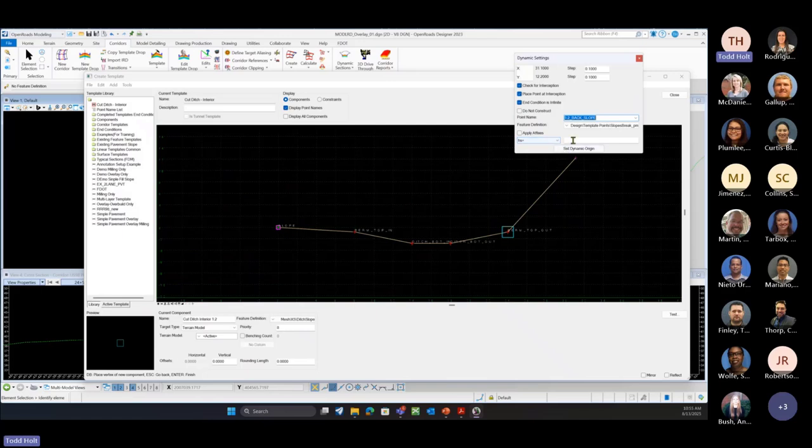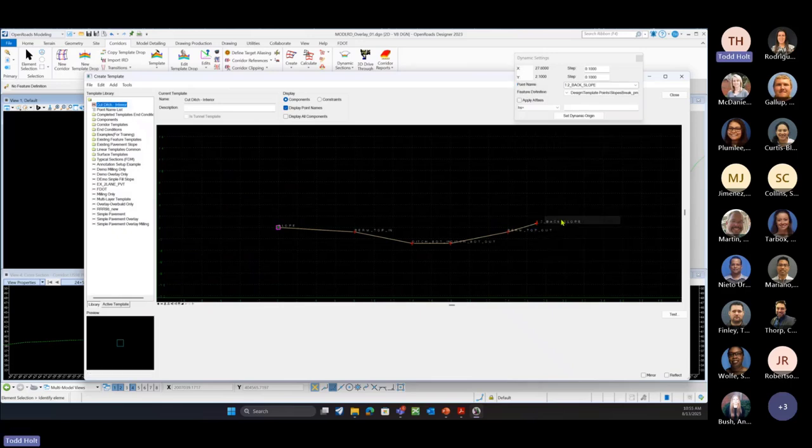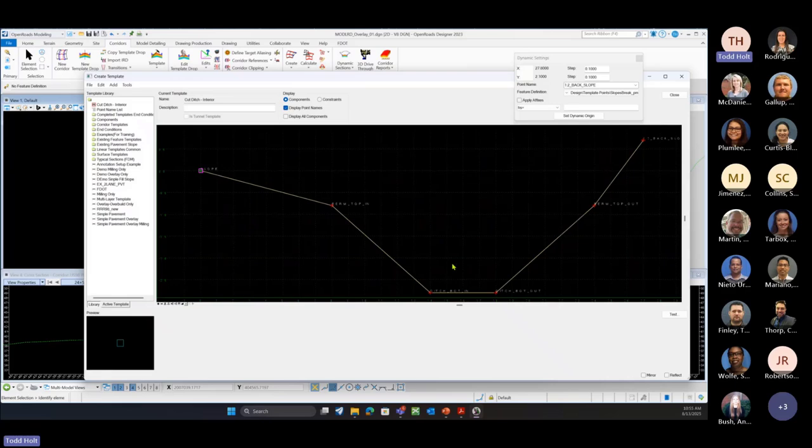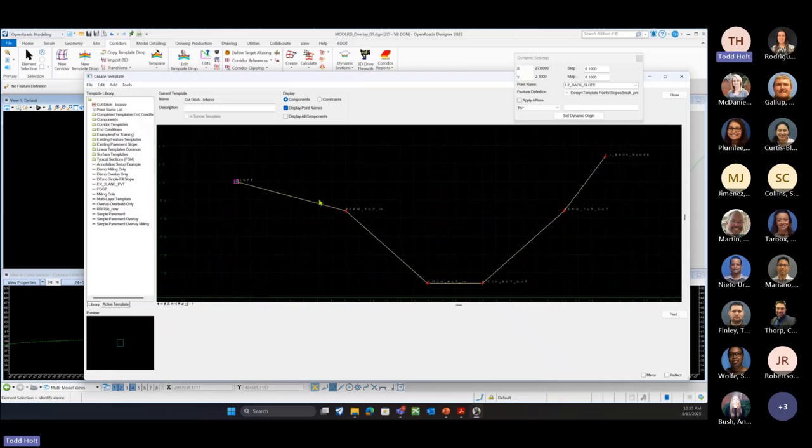And we're going to set this, we want it to go 3 feet at 50%. So we're going to put 3 comma 50. Right click, and then we're going to end and finish our ditch. And we can fit view on that. So there we have our ditch.